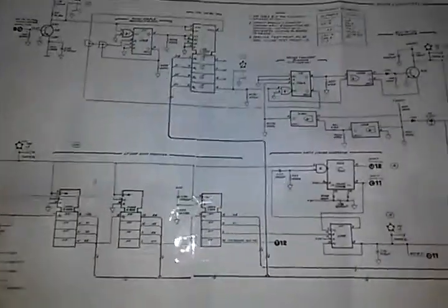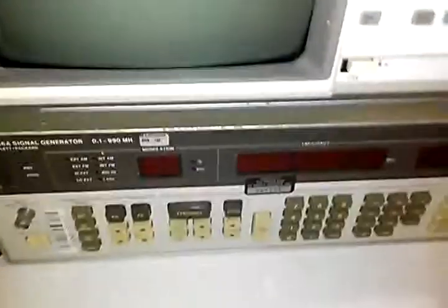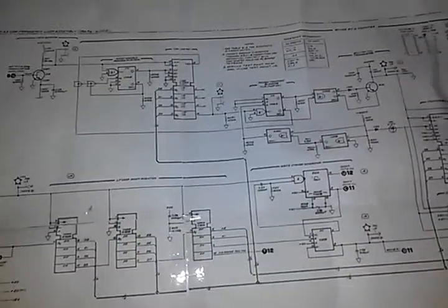Now, if you refer back to the previous repair videos, basically the failure mode for this device is that it was not centering properly per 100 hertz divisions. In other words, if you moved the frequency 100 hertz, it basically would move about 6 megahertz.